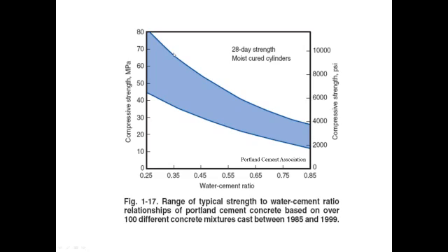And they're also very fluid. But if you just took an ordinary concrete mix design and added water, and it came out of the truck at a 0.50, which is not that uncommon, and then you added water to add workability, you shift it horizontally, and all of a sudden you're riding that blue line down, and you might lose half your strength. You might lose a quarter of your strength just to gain a short-term workability. And I know you folks who make your own concrete mixes are more concerned with the properties of your concrete, because you're going through the effort and the expense of making your own mixes. But it's certainly something to keep in mind, especially if you're dealing with bad concrete mixes.